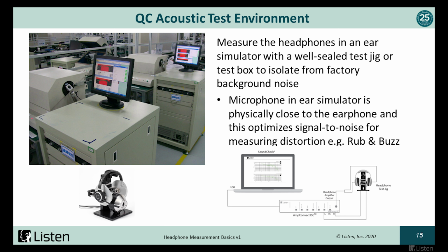And if necessary, you can put it inside an acoustic test box. But if you have a good seal, because the earphone is so close to the measurement microphone in the ear simulator, you generally get a pretty good signal to noise ratio. But if you want to measure rub and buzz, you might need to put it inside a well-sealed box as well.